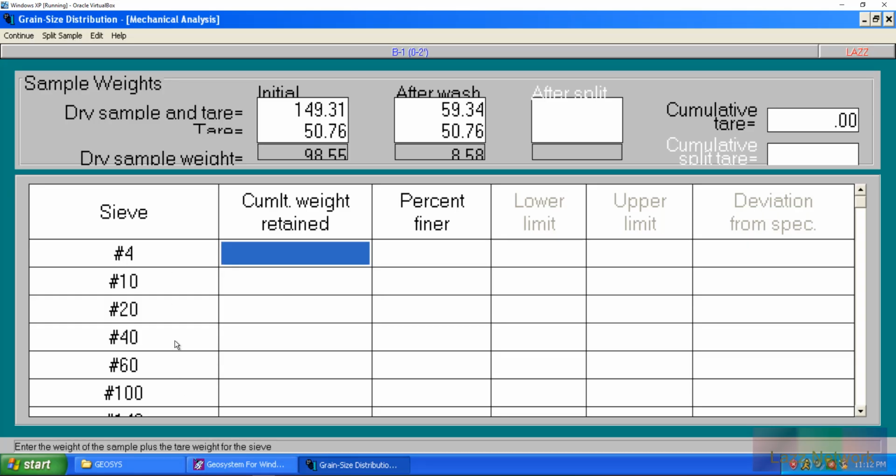A sieve set is determined either by the engineer or by the laboratory themselves, for however they want to sieve the material. So technically for a lot of specifications, like if we did the full AASHTO T88 hydrometer, your only sieve requirements are number 10, number 40, and number 200. I was close, I just needed to add the 0. So number 10, number 40, and 200. Technically you could do a sieve on just those 3 sieves and then there you go.